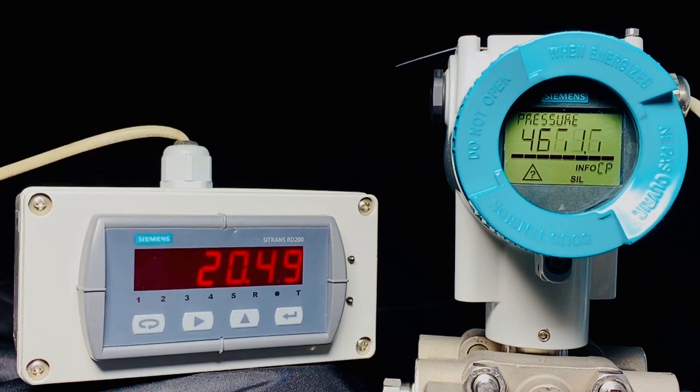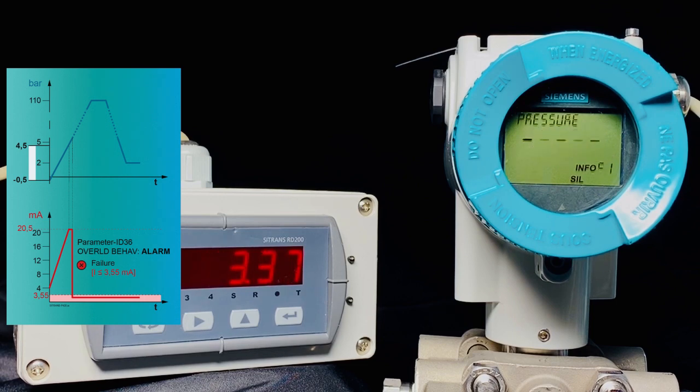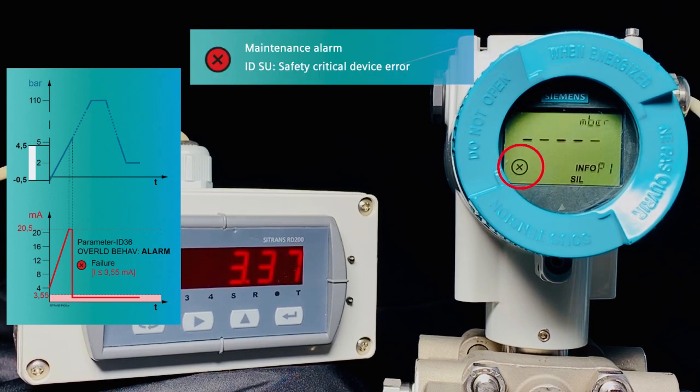If I increase the pressure further, the NE107 symbol circle with the cross appears, which stands for device status failure. Info displays SU, safety critical device error. The current is less than 3.55 mA.